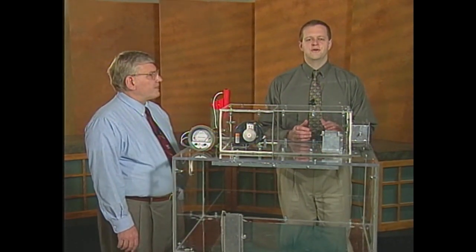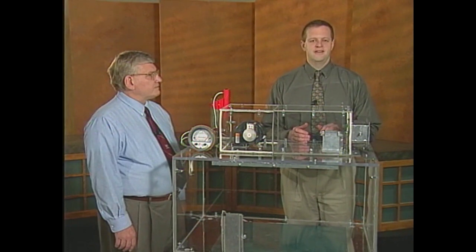Well, during the cooling mode, the system brings in the minimum quantity of outdoor air required for ventilation. If the building envelope is leaky enough, natural relief may be able to prevent building pressure from becoming overly positive in this mode. In the integrated economizer mode, however, the system brings in 100% outdoor air for free cooling, and building pressure rises.